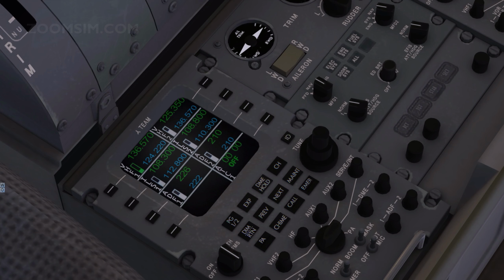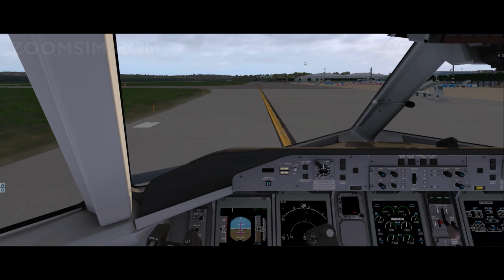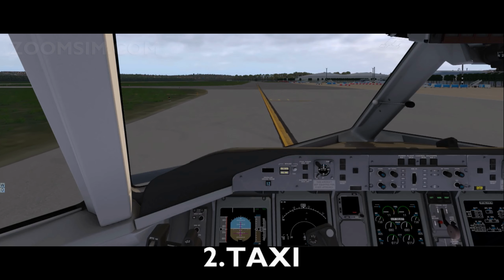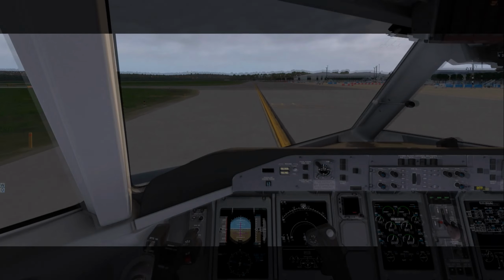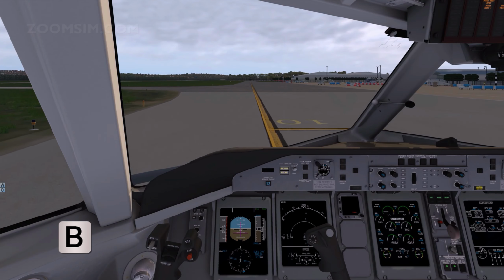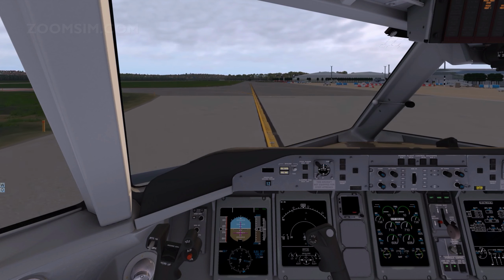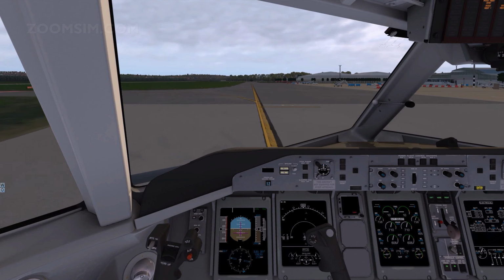Transponder TCAS Alt on. To set the transponder to standby, press the side key. Then to enter the desired transponder code, rotate the inner and outer tune knobs. Release the brakes. Brakes, check. When in motion, briefly apply the brakes to verify correct operation.